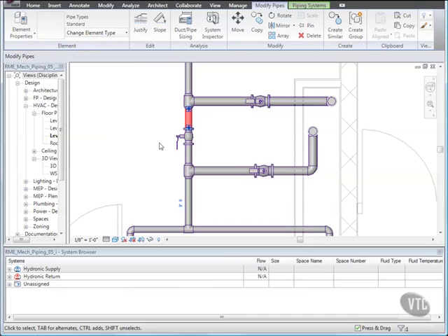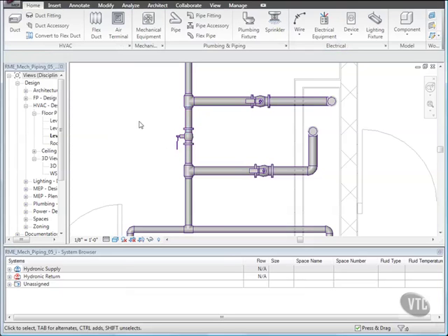Clear the selection and understand that currently the system is designed to run in cooling mode. You will add valves to the cooling tower to enable the system to alternately run in heating mode. In heating mode, you want to shut off the flow of water into the cooling tower. You will bypass the cooling tower with hot water coming from the boiler.